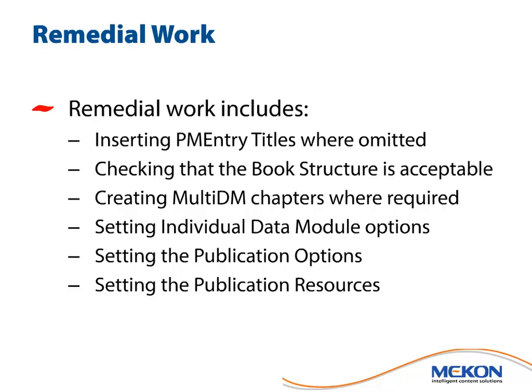Having imported the publication module in and done some restructuring, what you need to do then is you actually need to insert the PM entry titles where they've been omitted, checking that the book structure is acceptable. And if you want to create multi-data module chapters, then you can create those at that stage. Then you need to set the individual data module options and set the publication options, and then set the publication resources. And we'll look at those last 3 in more detail.